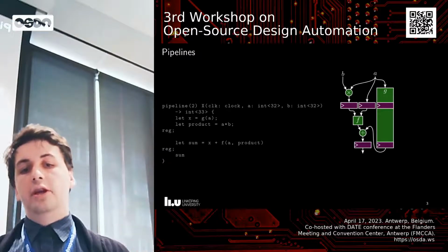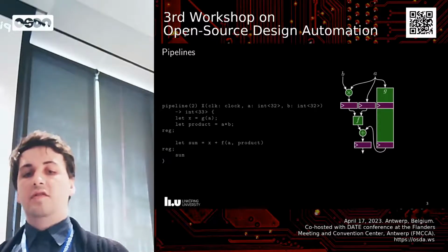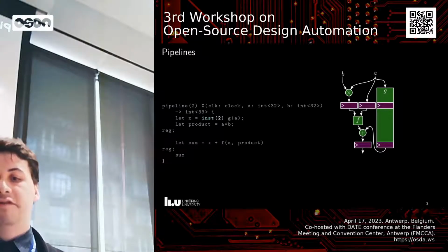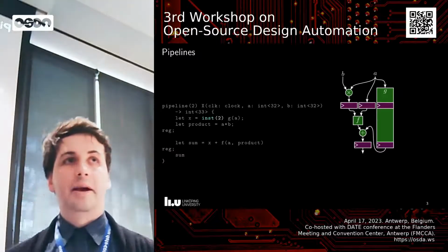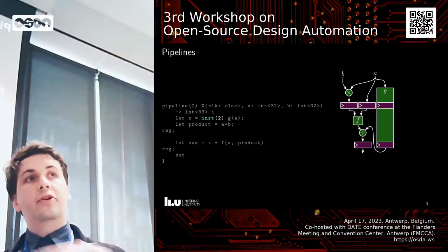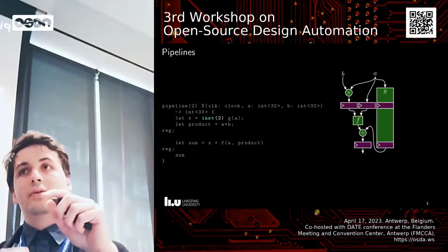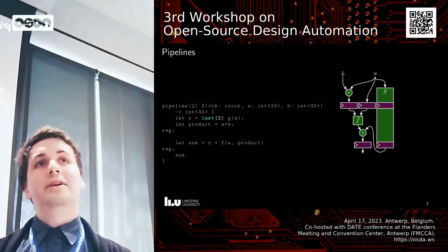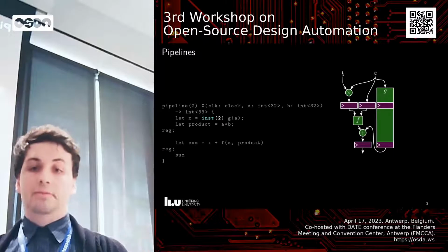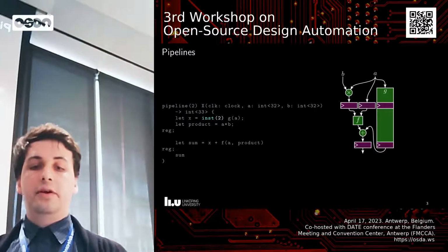And normally you would have to do a bunch of thinking now, like what do I have to change because of this? In Spade, because the compiler knows about pipelines, it will first tell you that you first need to instantiate this G block as a pipeline. And you specify the depth there. If there was more complex behavior here, the user would need to go back and check, and either change the circuit to match a new description. In this case, the compiler will actually figure out the problem for us.